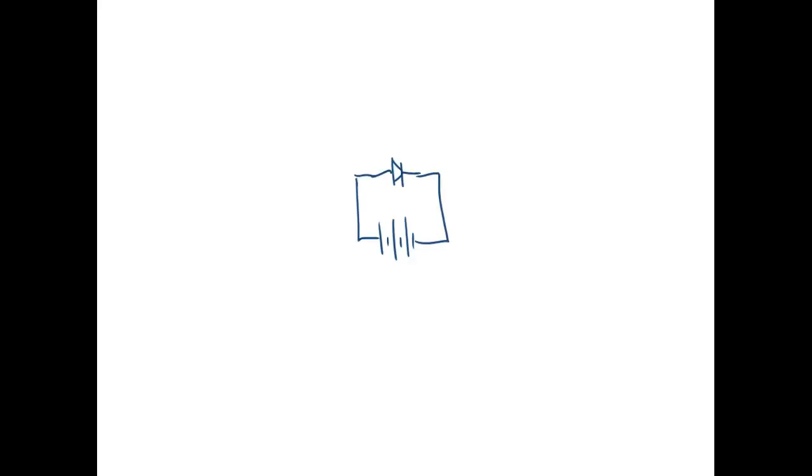It'd blow that diode just like that. Because once it's forward biased, it is a closed switch. So anything above 0.7 of a volt would be a short circuit. Y'all understand that? So what would we have to do?